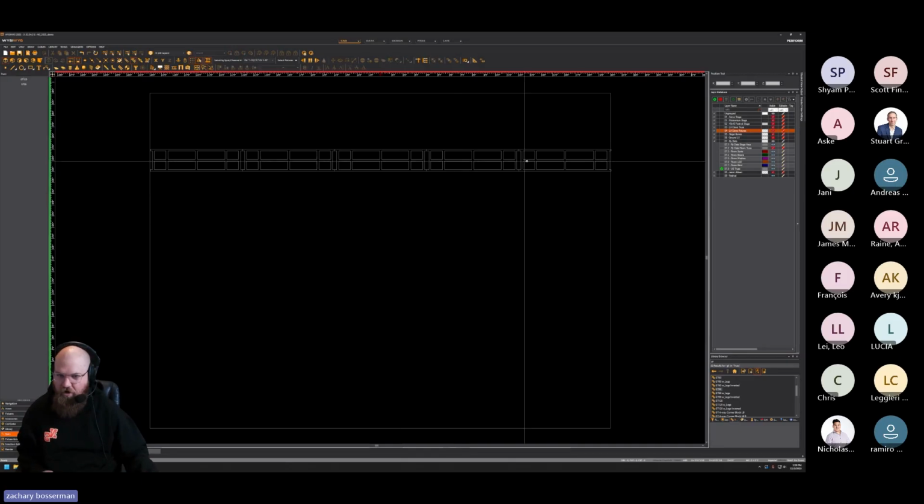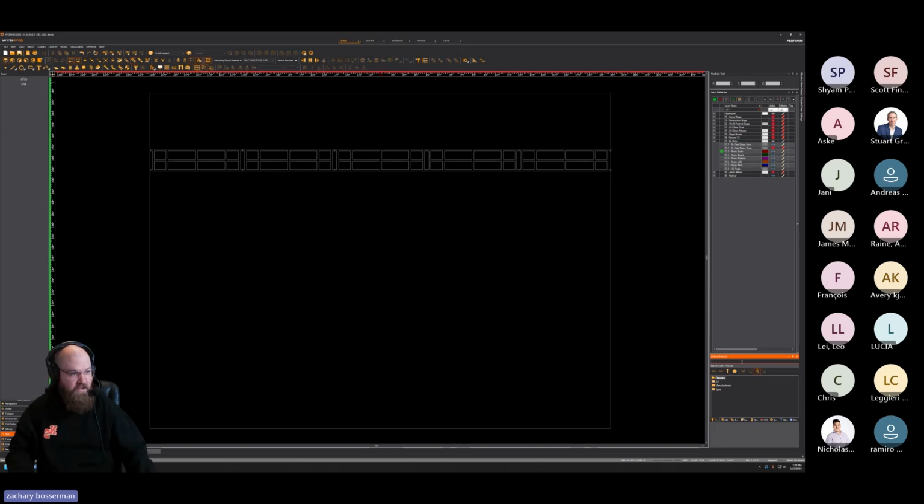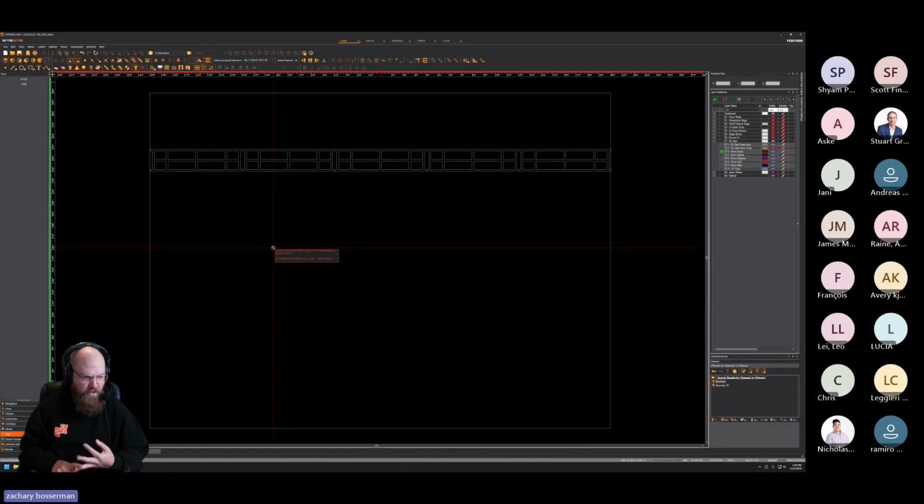So we've got our trusses here. And now we're just going to place our fixtures. We'll start on the layer I have here that is flown spots in my Flight 8 package. And we're going to grab that. So for this, I'm using the Ayrton Cameleon. So we're going to grab a Cameleon. If you notice, I have not yet talked about the modes for the fixtures, whether they're the right DMX channels. I get into that later. What I want to do first is just place the fixtures.